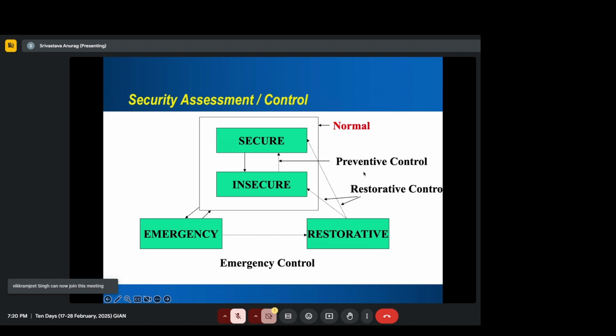So now, in the real system, which means that we are operating in normal condition, we are coming with secure and insecure conditions a few minutes before it happens. So we run the security analysis every few minutes, 5 minutes, 10 minutes, 15 minutes before. And remember that we talked about two things. So there are limit constraints in steady state, and then there are limit constraints for the stability.